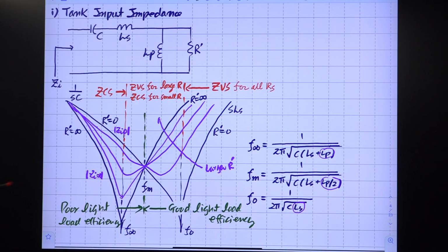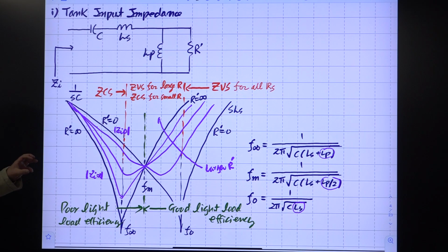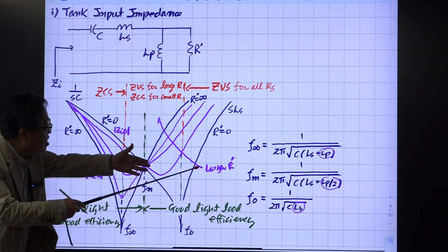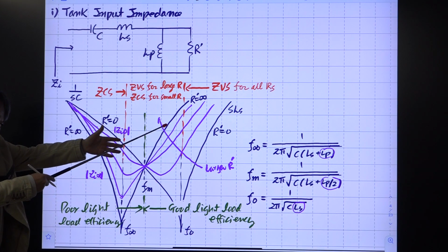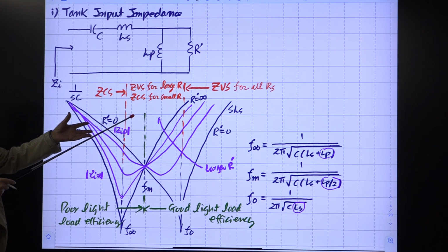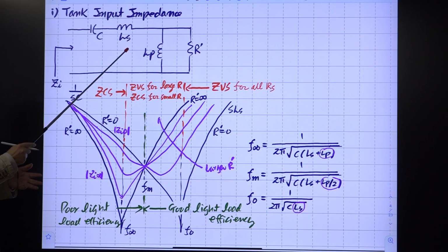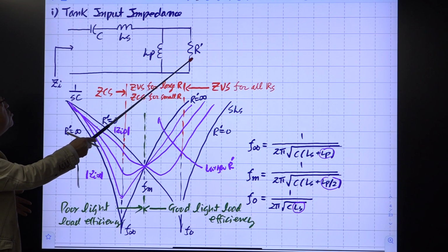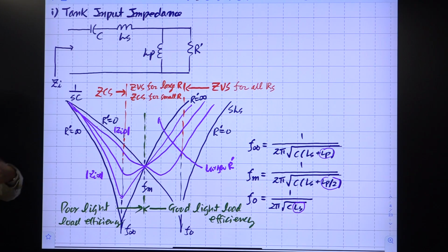If R is increasing, this load current will be very small, right? Then if R is increasing, the magnitude of the input impedance is increasing as well, which makes this tank current very small. Okay? So this is reduced. Suppose this is reduced, but if this IT is increasing, there is a huge conduction loss. All right? That is the case for this region.